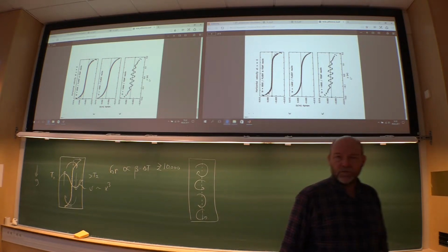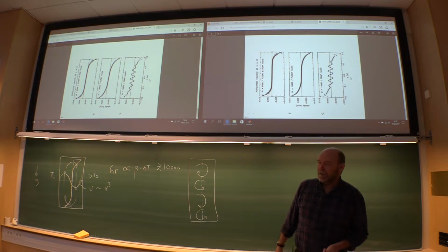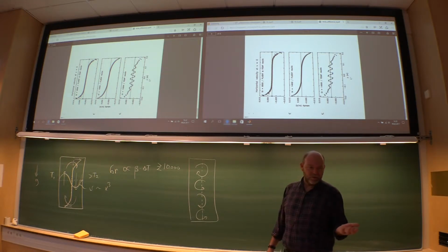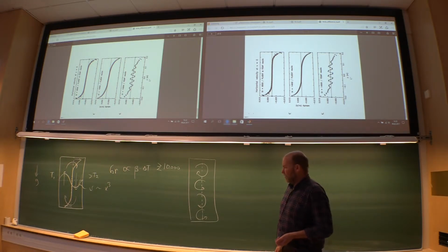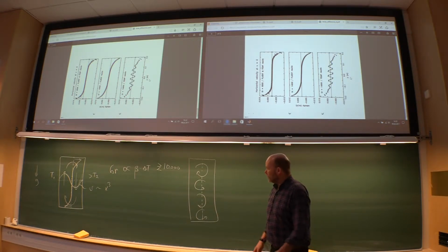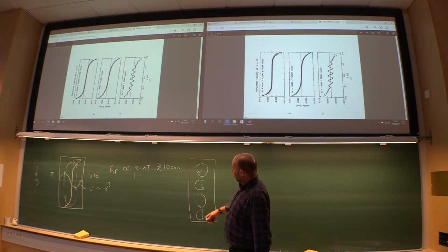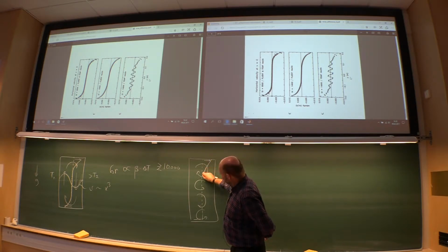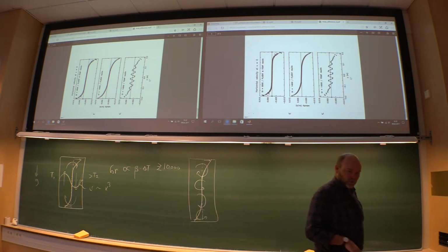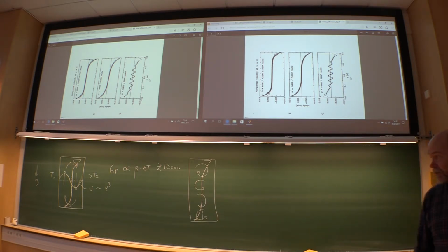Fluent in those days used upwind schemes. Remember, Fluent was an engineering tool and still is, so it's very stable. You give it the most stupid input, it gives you an answer, sadly. And in those days, for this problem here, it gave you the same answer. Actually, the effect was spreading it out a little bit. So it took this correct solution and sort of smeared it out so it totally disappeared. It didn't get the breakup at all.